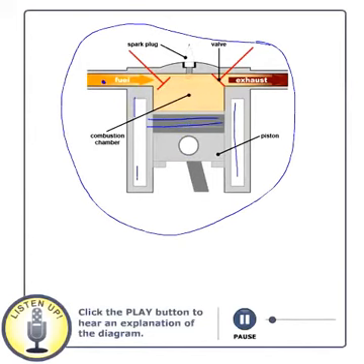And we have two inlets. One inlet is for fuel and air to come in as a mixture, and this is a valve that opens and closes. And there is another outlet here that takes out the exhaust gases, and there is another valve that opens and closes at appropriate times. And when the fuel and air mixture is inside, this spark plug provides a spark to ignite the mixture.